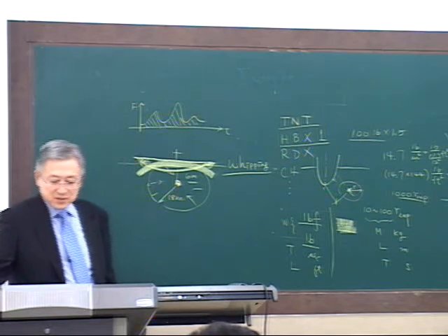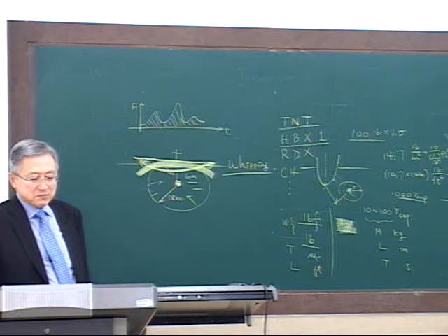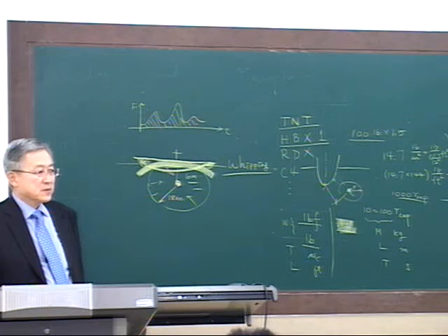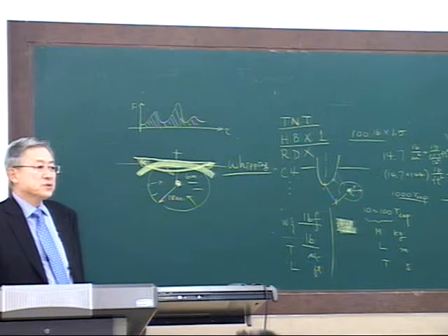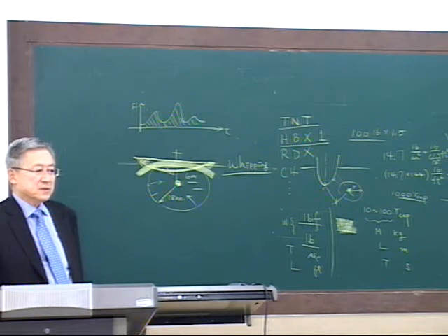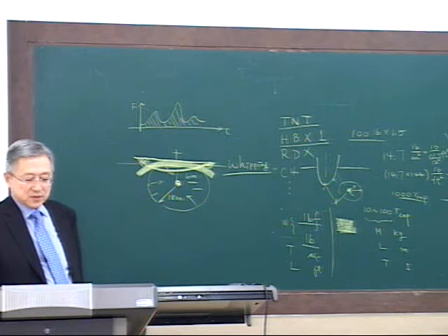So the linear impulse is the change in momentum. The force is the buoyancy force, so summing up from 0 to time t, force dt. And the initial momentum is, of course, 0. Initially, there is no gas bubble. Then start from 0 to time t. m_t we computed, so you end up having this relation. Then you plug in what you have done.